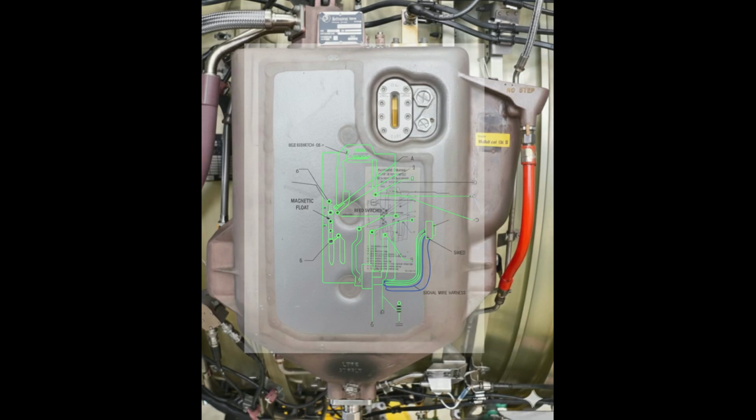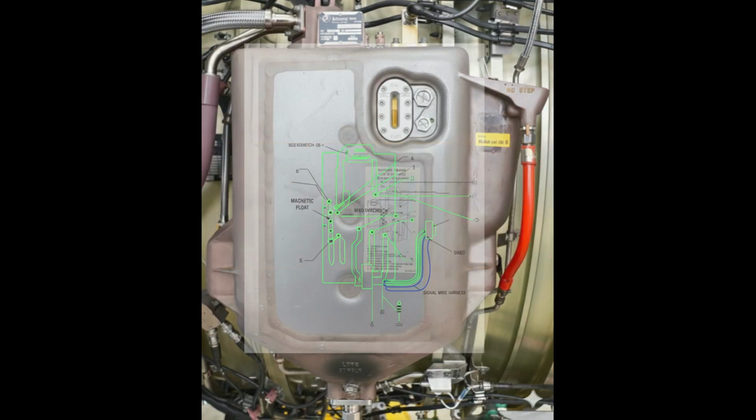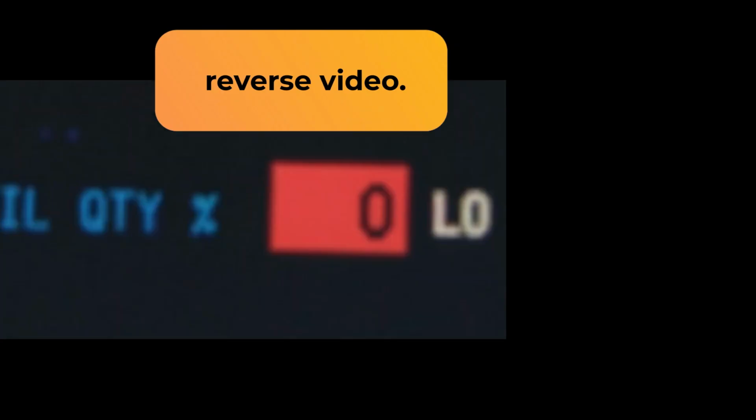5. Low oil quantity and reverse video. A low oil quantity alert occurs when the level drops below 4 quarts, in other words, 3.8 liters. Reverse video. The quantity value is displayed in reverse video. In cockpit displays, where text is usually light-colored on a dark background, reverse video swaps this to dark text on a bright white or amber rectangular background. This acts like a digital highlighter to ensure the pilot immediately notices the critical value among other data.